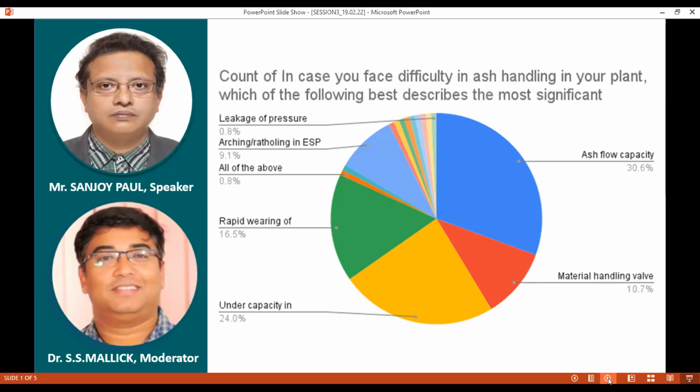Yes, and I also want to add that in the air receiver, which I have found, the auto drain valve does not work properly. So this area needs to be properly maintained, because when some water gets precipitated in the air receiver and the auto drain valve does not work properly, this moisture carries with the air. So this area is also to be looked into.